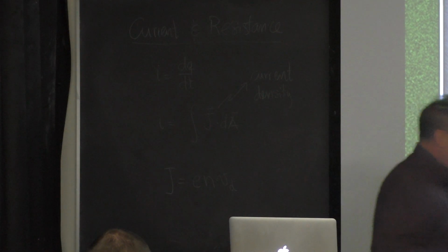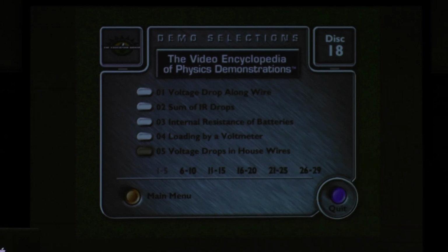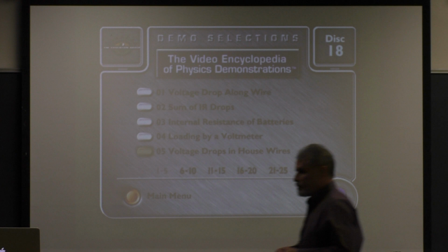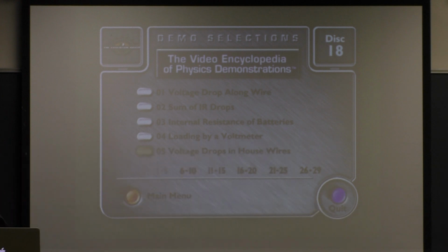Let's develop a little more insight into this chapter by looking at some of the questions. Sir, question about the I squared R. Because those two were connected in series, they had the same current, so you'd use I squared R. If they were connected in parallel, they would have the same voltage, so would you use V squared over R? Yes. That's how to view the problem.